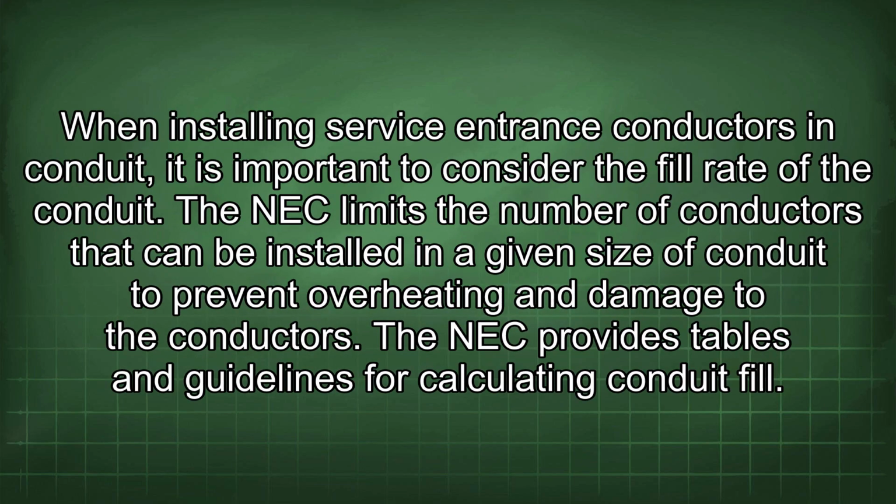When installing service entrance conductors in conduit, it is important to consider the fill rate of the conduit. The NEC limits the number of conductors that can be installed in a given size of conduit to prevent overheating and damage to the conductors. The NEC provides tables and guidelines for calculating conduit fill.